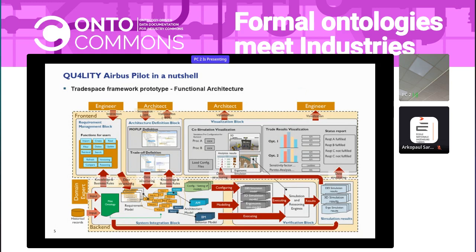That's an industrial requirement, and we need to find an assembly process that can be suited to manufacture 150 aircraft per year. With that, we have different architecture options, the assembly sequence options. And we run some simulations, for example discrete event simulations, to check that we are able to do that. And then we trade between the results.